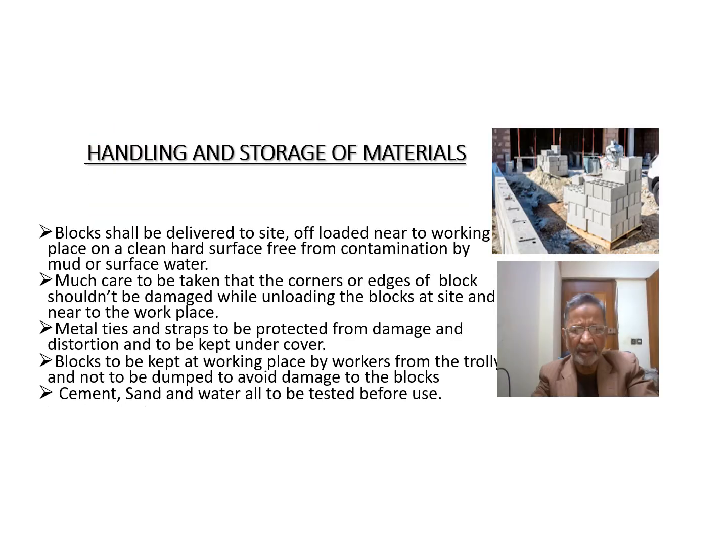Thank you. In slide number 7, we'll discuss the handling and storage of materials at construction site for the masonry. Blocks, bricks, stones, or any other material used for the masonry should be loaded just near to the working place on a clean and hard surface, free from contamination of the mud or surface water.